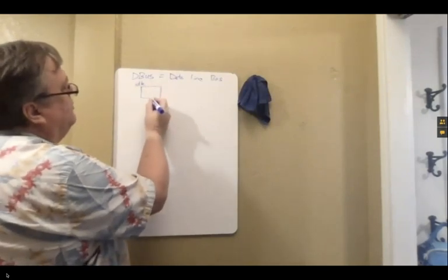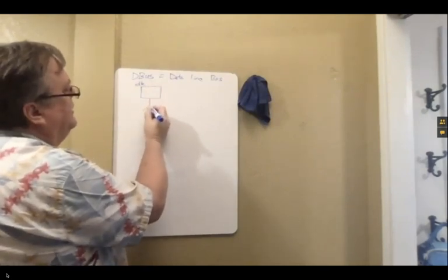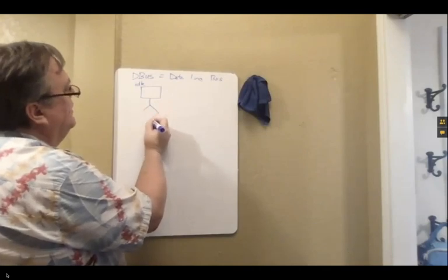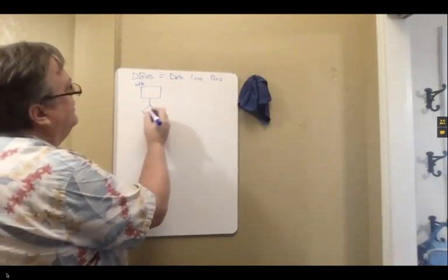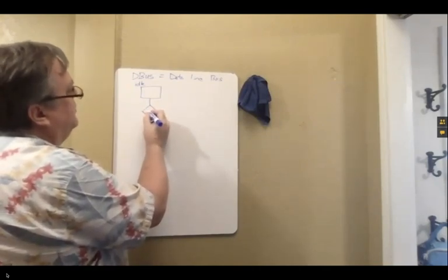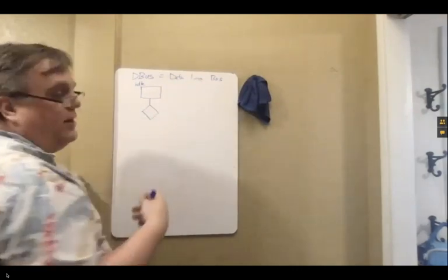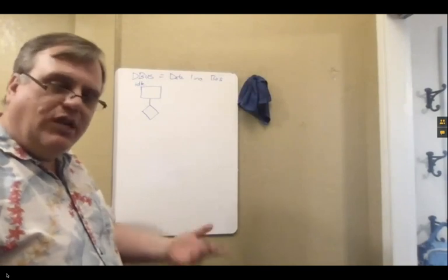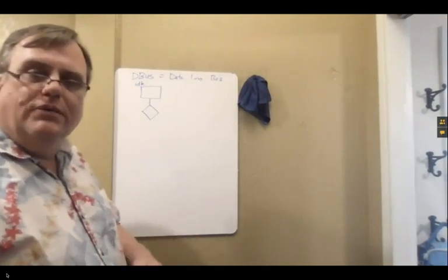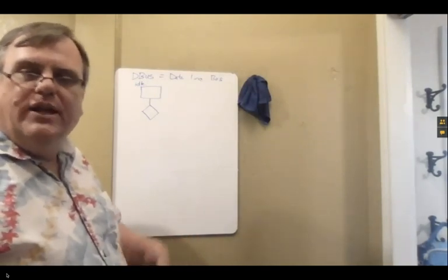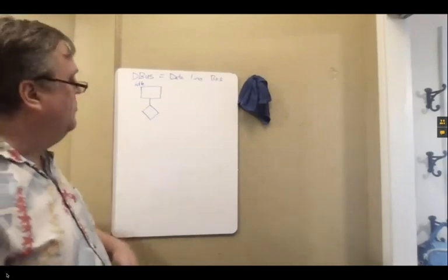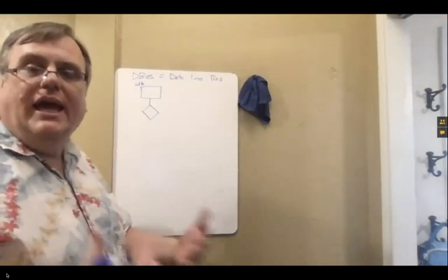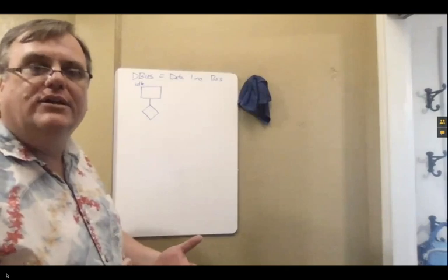What I want to do is actually check to see if the data on the bus is actual real data. So normally the bus will be Z if there's nothing there. There's no assertion. But if there's a 0 or a 1, it goes high or low, then I know, hey, some new data is coming in.